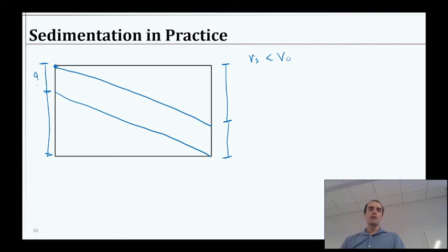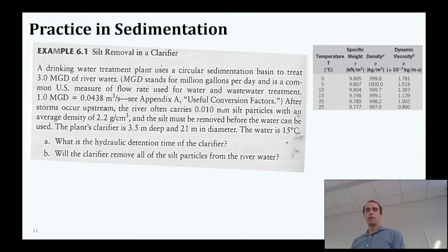This could be section A, and this is section B. Well, that's going to be B and A over here, just based on basic geometry. So that's pretty convenient, and then we know, okay, well, some portion B is removed, and that leaves some portion A that never got a chance. They all escaped. So that actually gives us a way to directly relate the settling velocities to the fraction of particles settled in such a system.